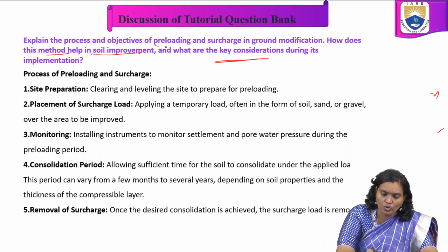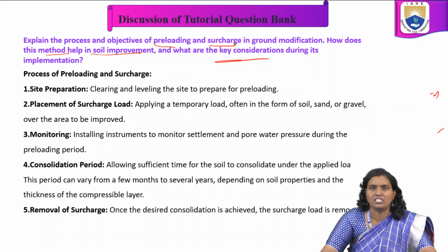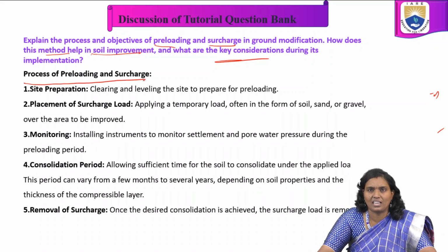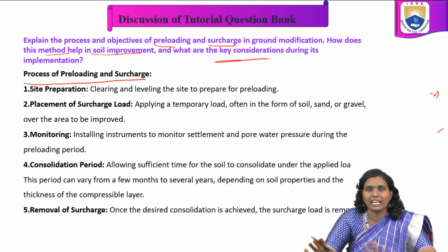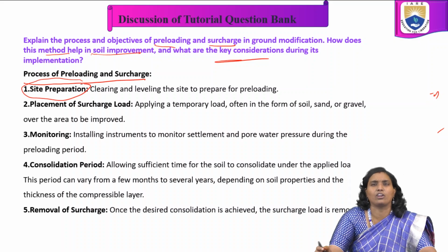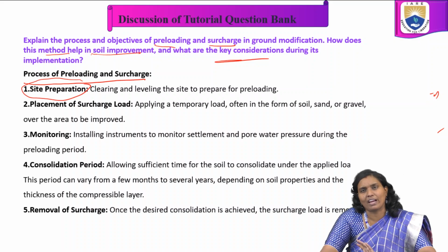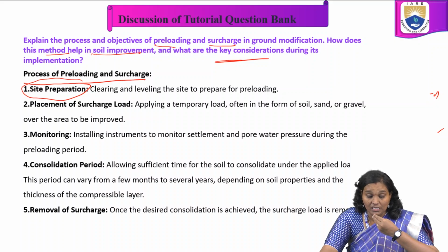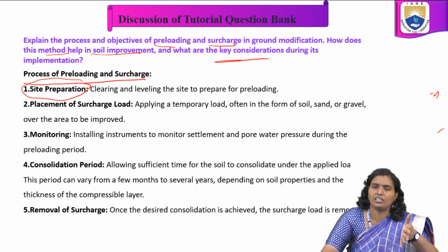The first thing they asked is to explain the process and objectives of preloading and surcharge. Here we have two different terms, preloading and surcharge. First we have to consider the process. Whatever the technique, the first step is site preparation, the starting process for any technique, whether it is mechanical modification, hydraulic modification, physical modification, or inclusions or confinement modifications.